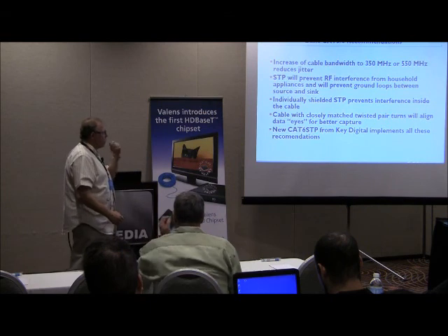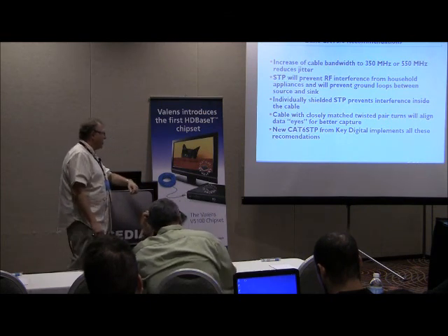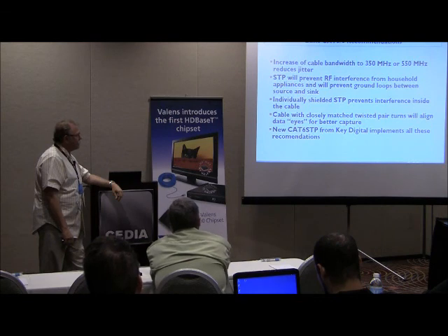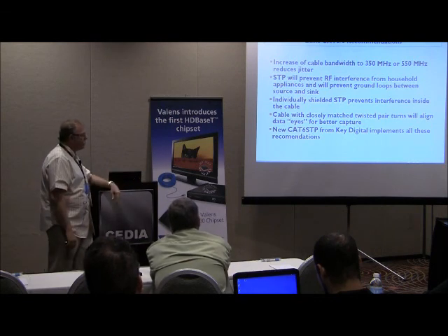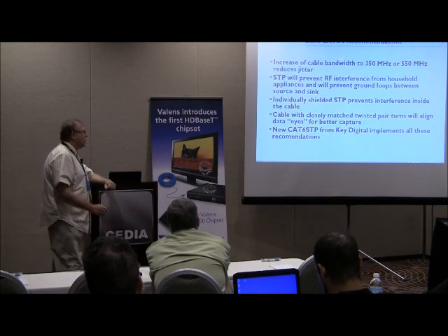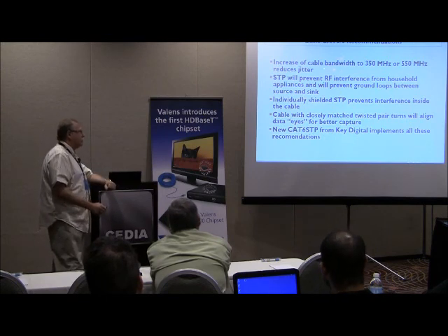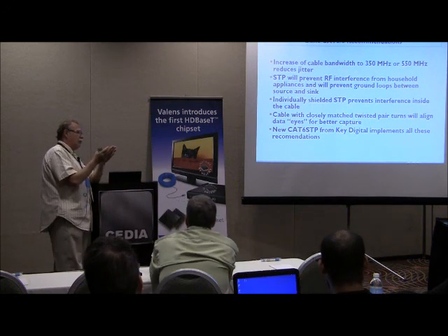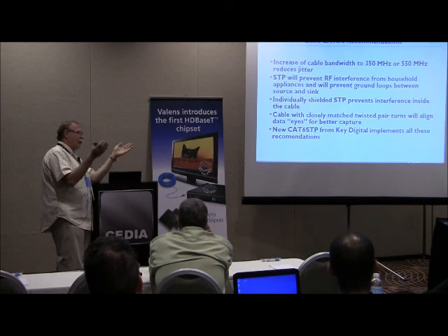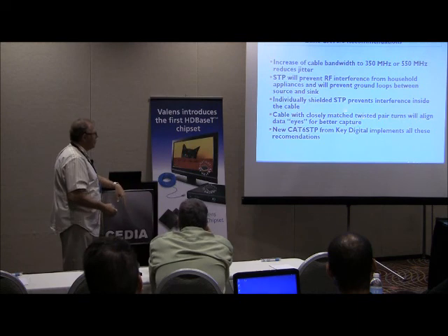So what about basic cable recommendations? When it comes to using Cat5/6 cables, for either technology you use, the problem and the trade-offs are very similar. The cable bandwidth plays the most important role. The higher the bandwidth, of course, the less jitter on the receiving end, so there's much more possibility to have the eye open, alignment correct, and your data recovery on the other end.